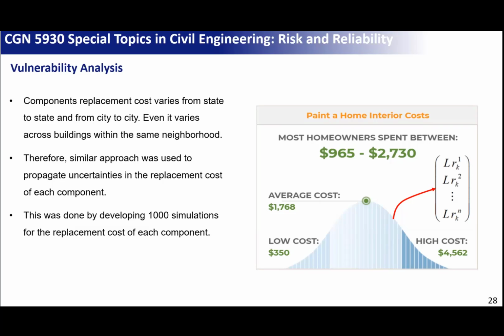Right now, I want to find the replacement cost of the component if I was hit by a hazard. So I have the probability of damage. Let's talk about the TV. If I have 0.3, what is the replacement cost? It will depend on the probability of damage that you will have. Here I will have, for example, a probability of damage of 7%. Will the replacement cost be the same if I have 1 meter of flood depth? No, because the probability that your TV is going to be damaged will be much higher. But at 0.3 meter, maybe the water will not touch the TV, so the probability of damage will be very, very low. But if you have 1 meter, the water might reach the TV.